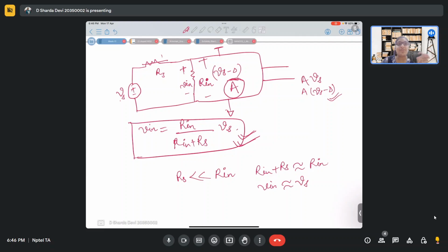That is why there are constraints for input impedance and output impedance. In all the amplifier circuits and analyses, we always do input impedance analysis and output impedance analysis, finding out the actual input impedance and output impedance. Why is it very necessary? To avoid this loading effect.